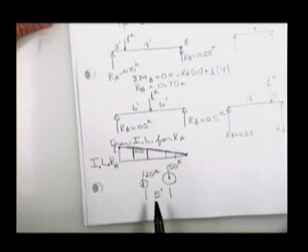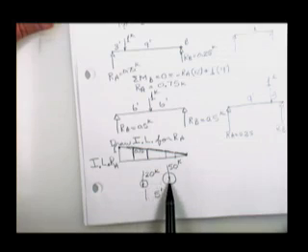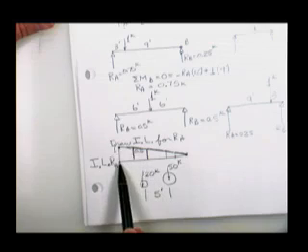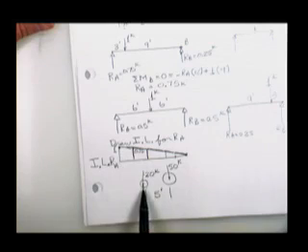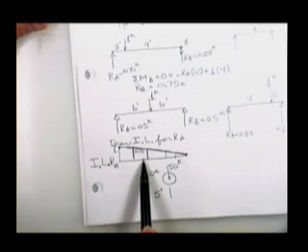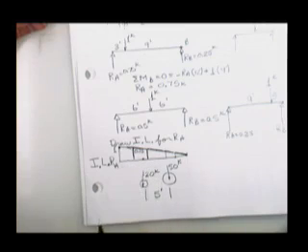Number one, to get the biggest reaction at A, would you have the truck going east to west? You wouldn't, would you? You'd turn the truck around the way I had it the first time, so the 50 kip load could be placed where it causes the most reaction at A, and then the 20 kip load would just go over here 5 feet and add this much reaction at A. It tells you where to put the truck. It tells you which way to make the truck go.